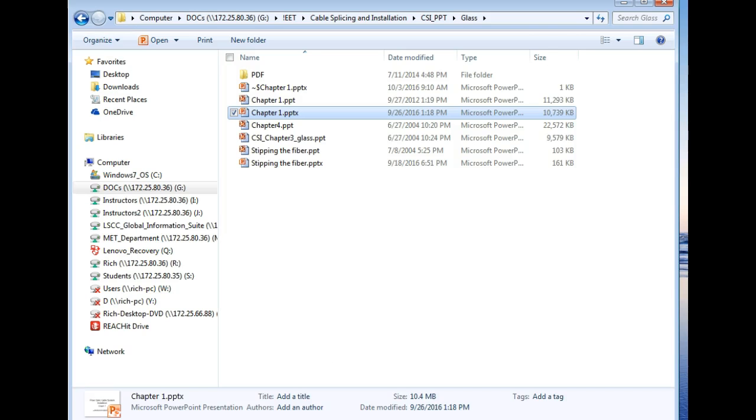What we have on this one is two wavelengths, and I don't remember. I'm going to have to look it up. This is 850 nanometers and 1300 nanometers, which should work for anything if I can get it to turn off. But here goes. This is a source for light when we check the meters out or check the cables out.